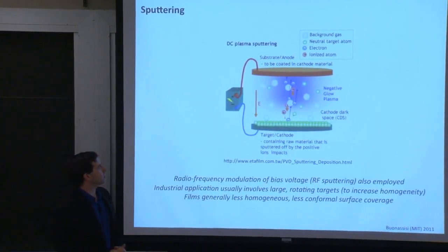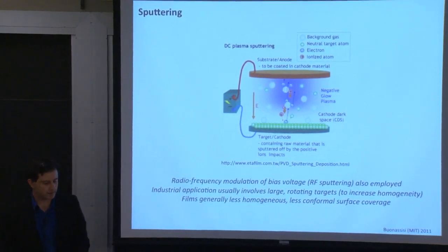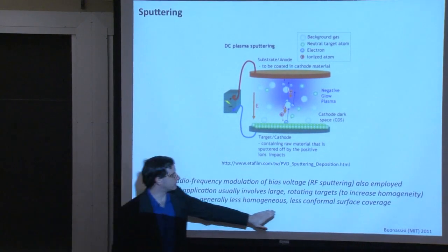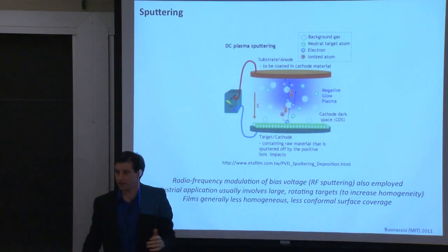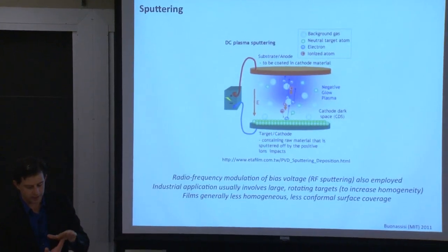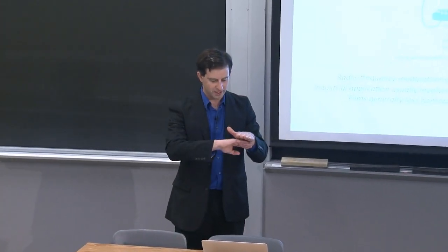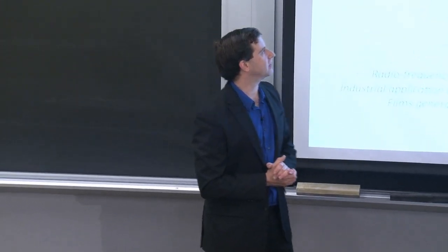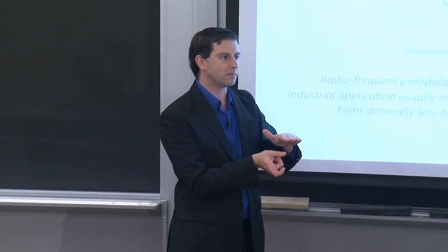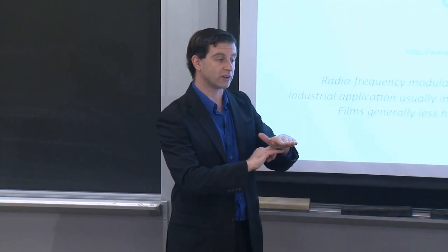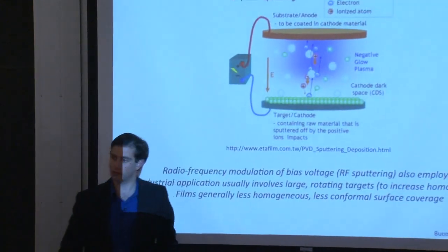So in terms of comparing sputtering against other growth technologies, there are technologies that are more conformal. Because this is more of a line-of-sight deposition technique, the atoms are moving toward your substrate, right? But if you have some shape to your substrate, maybe you have a ledge or ridge, in that case, you won't necessarily coat that uniformly. You might have less being deposited on that edge rather than the flat sections. And so conformality of coverage, or conformal surface coverage, can be an issue with sputtering.